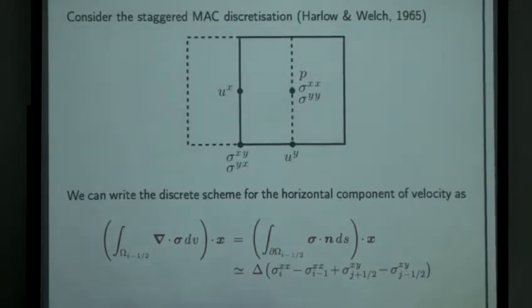If you do that, of course it is going to be momentum conserving. Why? Because the neighboring momentum control volume is going to have the same term with a minus sign, so everything is going to cancel out, okay? So not only is it consistent with Cauchy's formulation, but it's also discretely consistent in a very natural way. You can even include the surface tension stress into your viscous stress or whatever, so you have a single stress tensor for both.